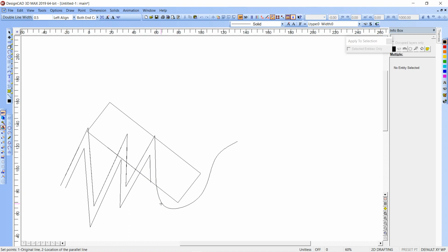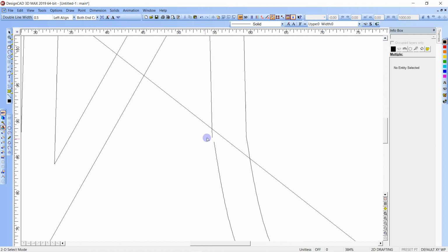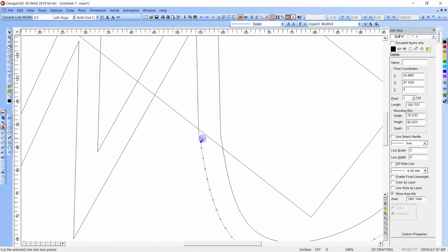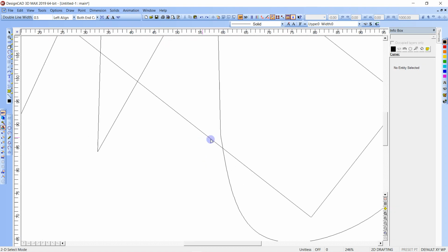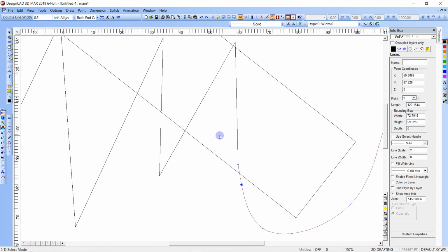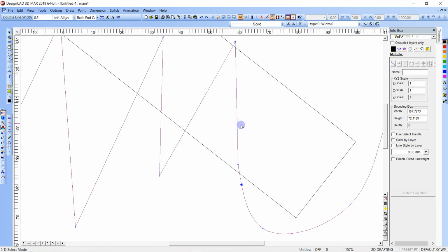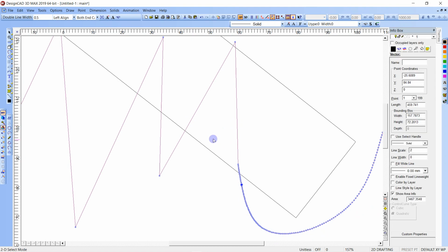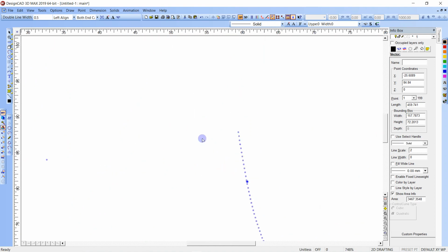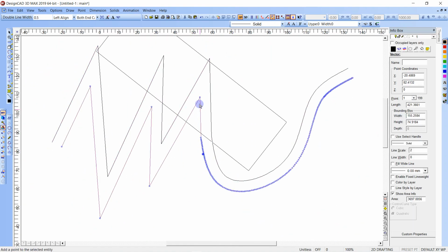Do that again, F3, hit it off of this one, and you'll see there's a little break. So in this one command I can trim it up pretty easily. Control Z. The better option would be to vector convert that: take this one, hit B, and then hit E, and it'll make a solid double line, no break in the line. And this is a solid polyline too.